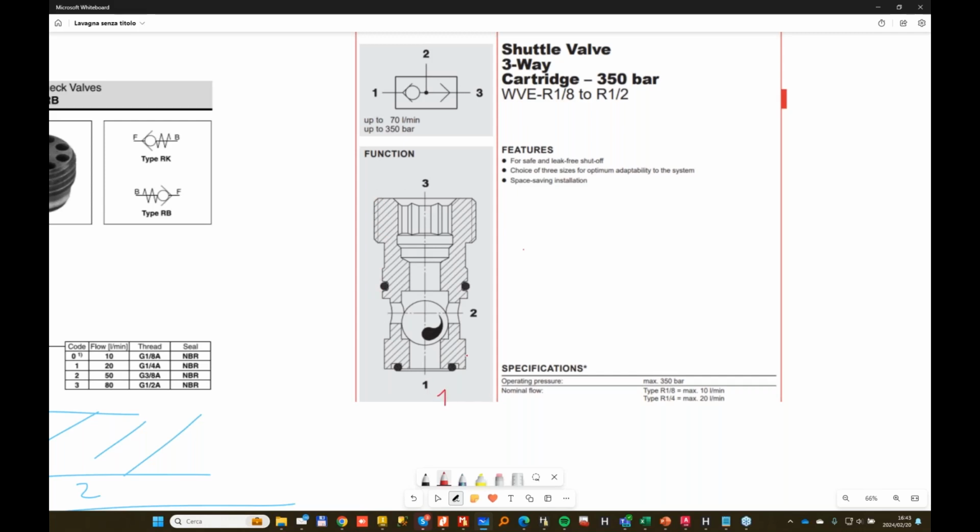So as you see, it's 1, 2, and 3. This is going to fit into a 1/8 BSP port made something like this with a flat plane, and then we have the drill. And on top here you could have another drill, and here you could have the same 1/8 BSP thread or a larger one. So what you need to do in this case is really use the same Orifice plug command on a 2-way cavity, 1, 2 cavity.